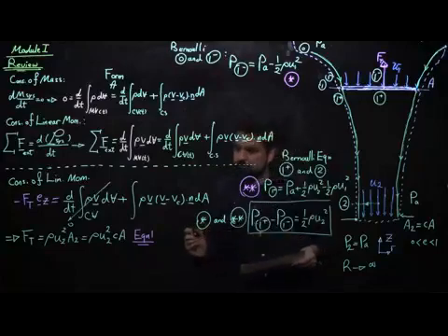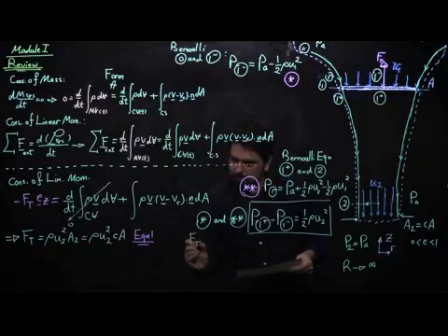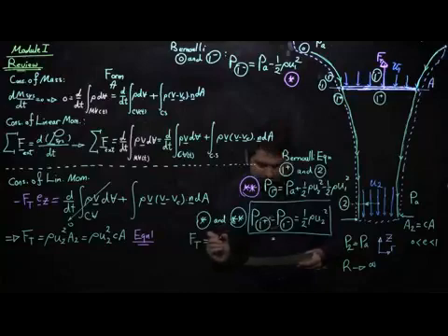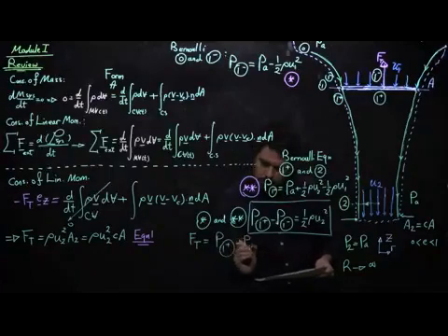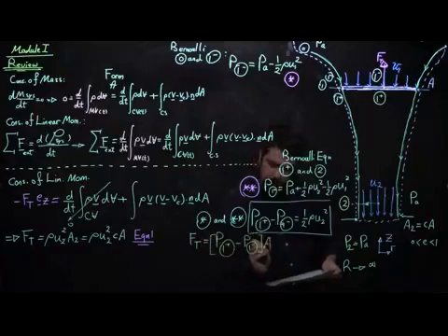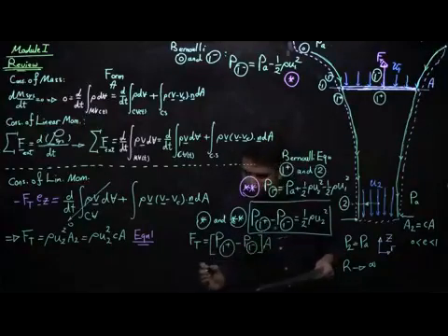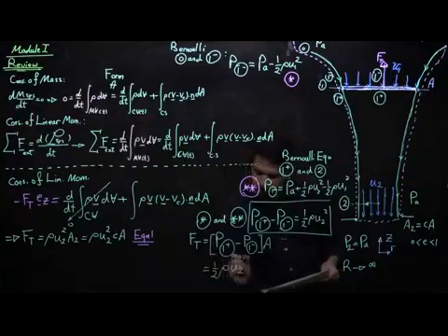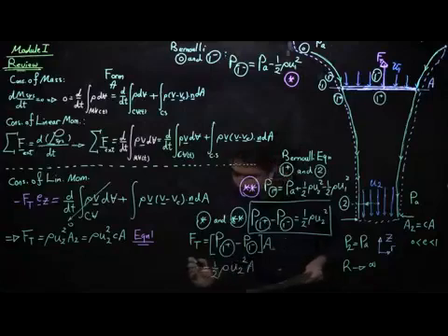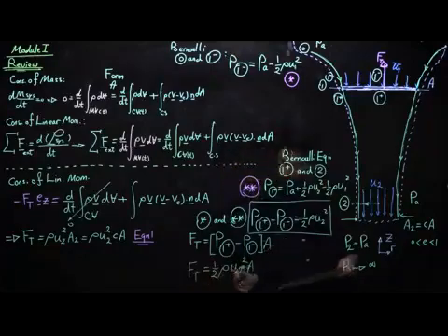So the thrust force can also be calculated using Bernoulli. That would give me the thrust force as P1 plus minus P1 minus, the entire thing in the brackets, multiplied by the area of the blade, and that would be equal to half of rho U2 squared multiplied by the area of the blade. And this is what I call equation 2.